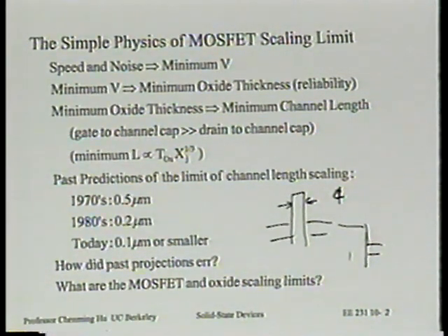But the funny thing is that from what we know today, this oxide quality is not only extremely good in this 30 angstrom and thinner regime, in fact, everything we see is as if it has the same property as thicker oxide in terms of barrier height, to the extent we can determine them, and dielectric constant. Nothing seems to be changing. Now, I personally don't know how to really justify why there's not more of a transition layer. But definitely, it's a very good transition.